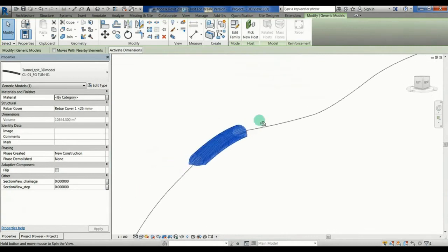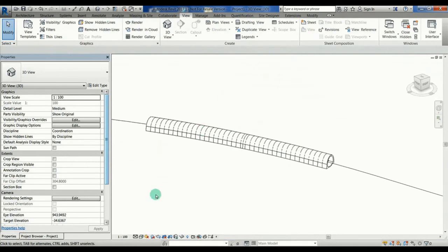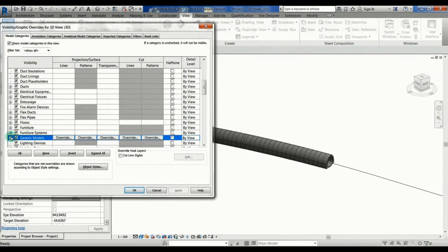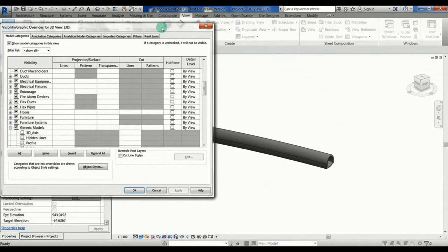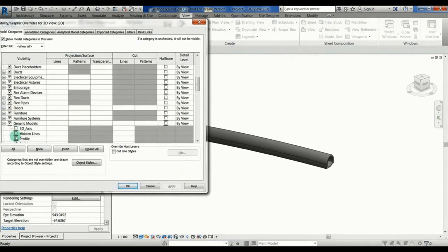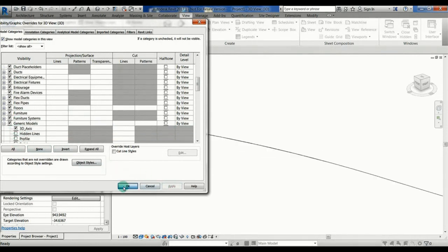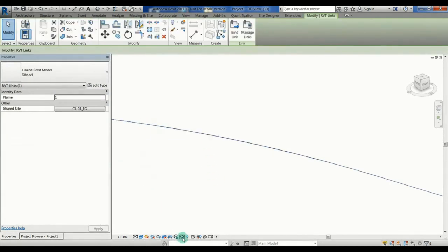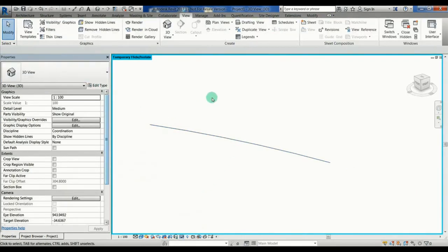Okay, so now we got a Revit model, a geometry, some information, and it's georeferenced. And I said that this 3D model is composed of the 3D axis, of a solid, of a profile. So I made some subcategories for visualization. If you just want to visualize the profile, it's possible. If you just want to visualize the 3D axis, it's possible as well. So it's the same object with different views of the same object. Okay? And the profile controls the 3D solid. So if I change the profile, it will change the solid, but the profile remains at the same place.